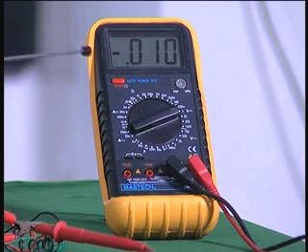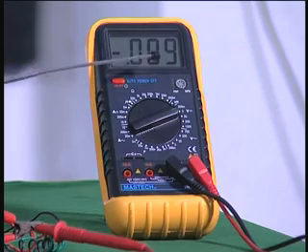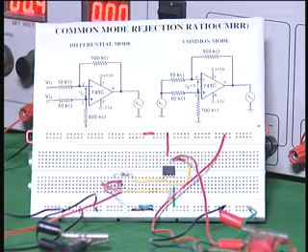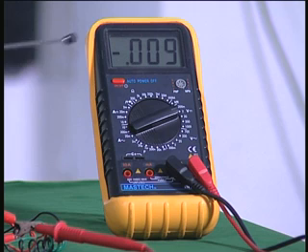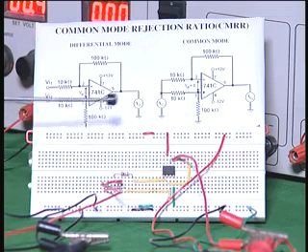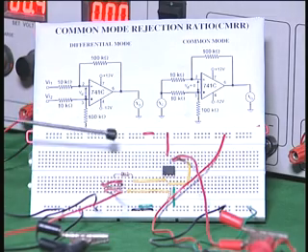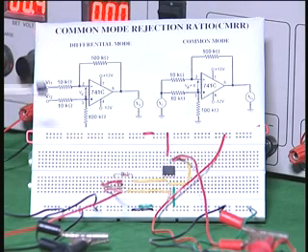So, it is a very, very low value, and therefore 0.009 divided by 0.5 is AC, which is going to be very, very small, and we already saw the differential gain is 10. So, 0.009 divided by 0.5 is about 0.002, and therefore you will get around 5000 as the CMRR. 5000 will be the CMRR, and in dB this will be nearly 80 dB, say 75 to 80 dB or so.